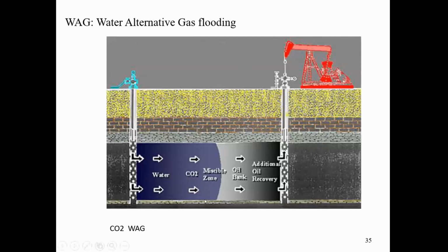So CO2 will reduce viscosity from one side in the miscibility, and also it will increase the K permeability, and the water injection will increase the pressure of the reservoir. So you have 3 gains. You win 3 wins. K is larger, pressure is larger, viscosity is smaller, and you achieve better. So remember, WAG CO2 is a good example of an optimal recommendation for tertiary recovery.